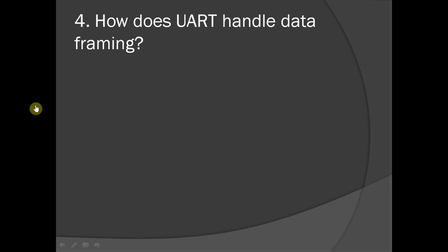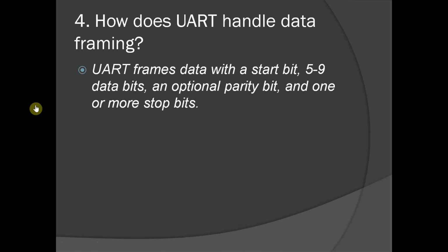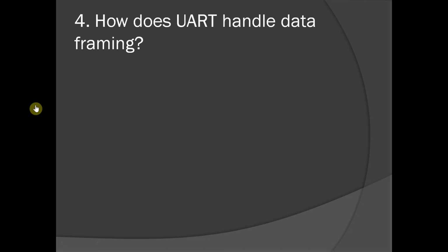Sir, I think in a UART module, there will be a component that converts data. Here, UART is getting parallel data from the system, and the parallel data is converted into serial data. So in UART, there can be a parallel to serial converter.